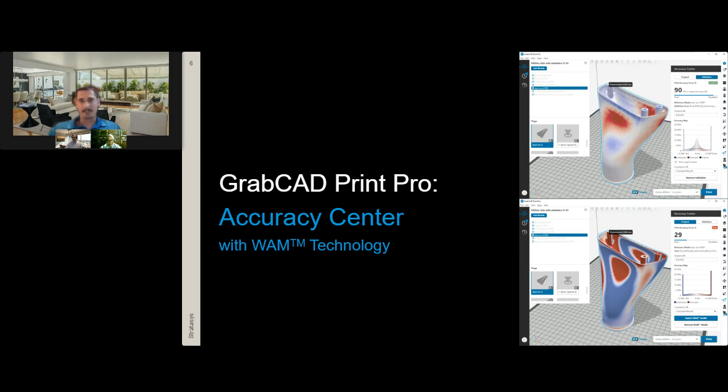Just kind of the nature of the process is we have some areas that shrink based off of the geometry. And so for these really complex parts, we're able to correct that deformation and, like I said, essentially pre-warp it. So when you build it again, it essentially warps into the correct shape. And so you can see the difference from the bottom to the top. That's, again, holding all things constant, using the same tolerance spec to generate that heat map.